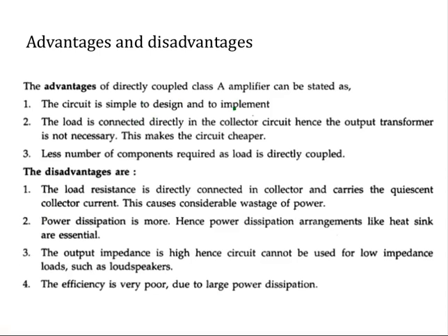What are the advantages of directly coupled Class A amplifier? The circuit is simple to design and implement. Load is connected directly in the collector circuit, hence output transformer is not necessary. This makes the circuit cheaper, and fewer components are required as load is directly coupled.